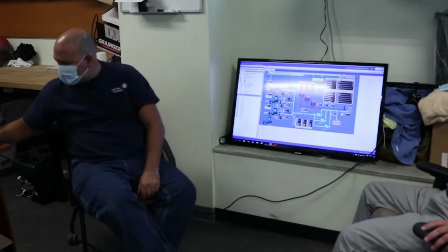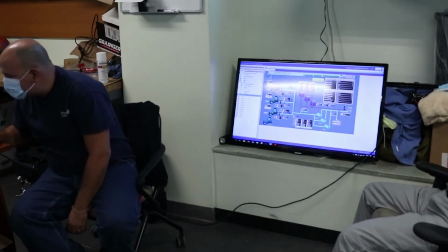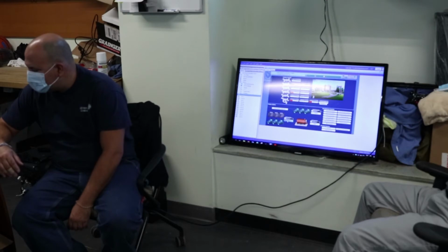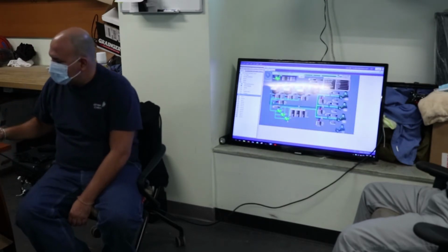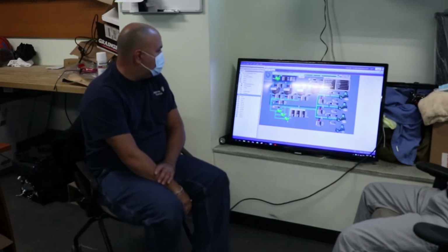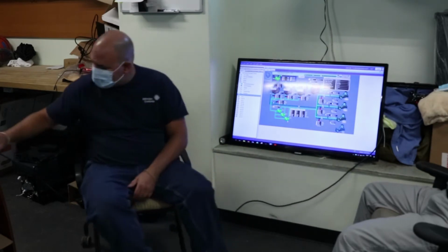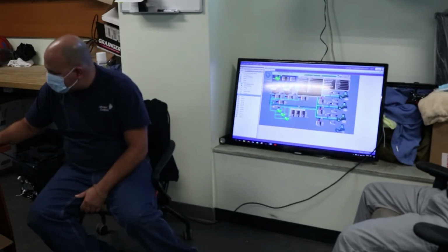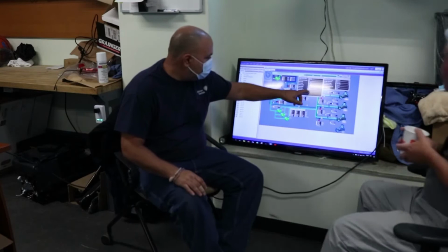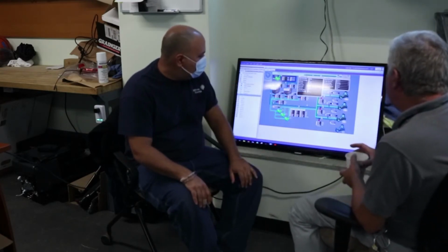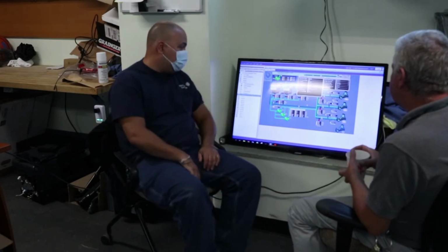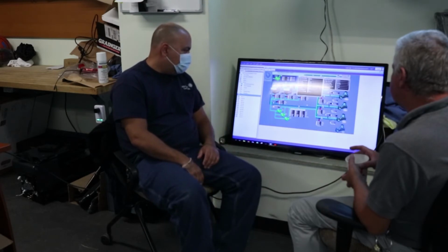I think when we get to it, we show the fourth. And also the primary chilled water pump number 4 should be on. So we have the future there. So what's the question? I think I put something in this drop down here. It tells you which is the lead tower, which 2 is the lead tower. So that'll be the first one to come on in rotation. I didn't put a point to tell you what's next, but they only called for which was the lead.